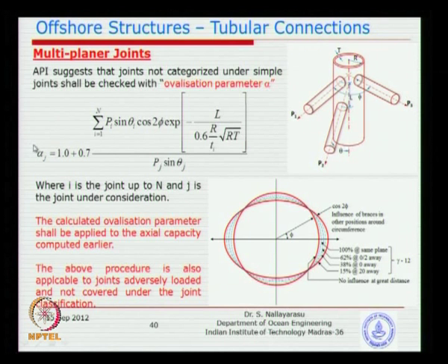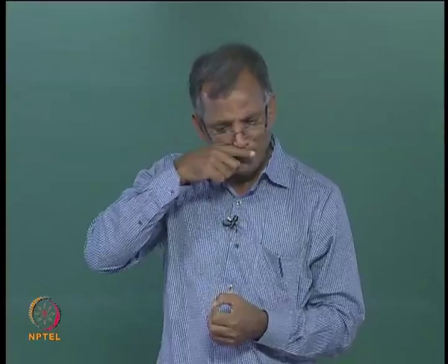If there is no other brace, the effect will be 1, and if there are a few more braces, this is the formula that you need to calculate, multiplied by 0.7. So, it will be incremental to that brace load, but of course in real design practice we do not use it. In research studies, especially experimental analysis, we try to use it, to study the effect of one brace on the chord due to various other braces in the vicinity.